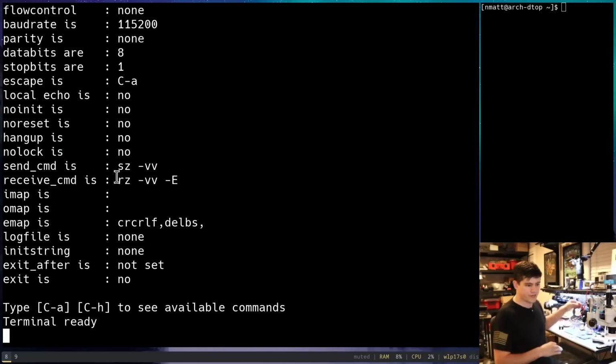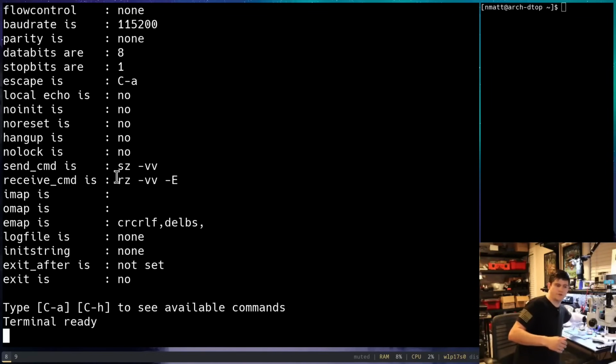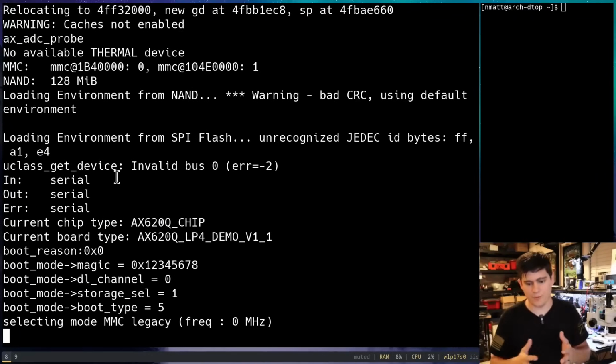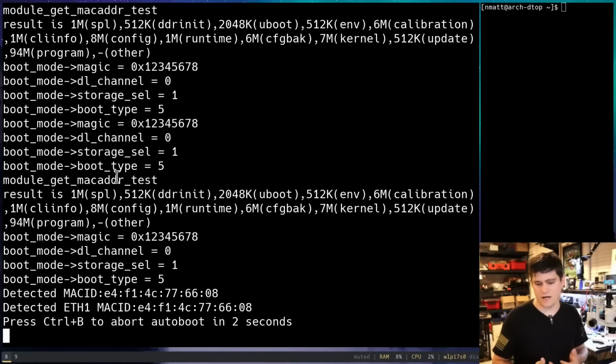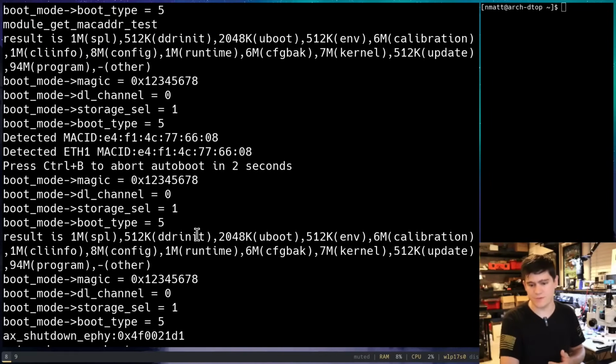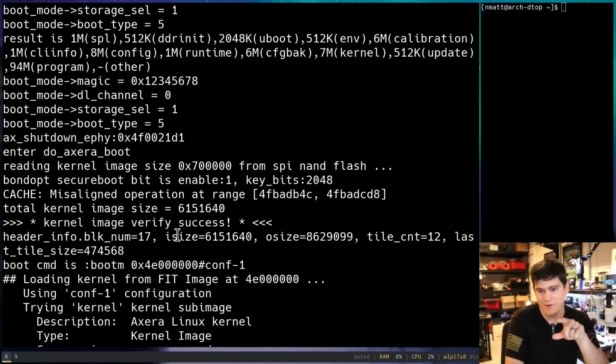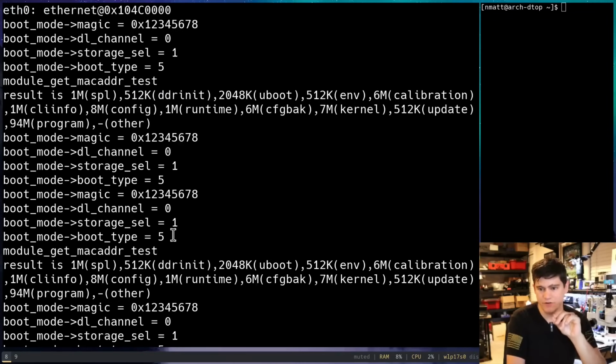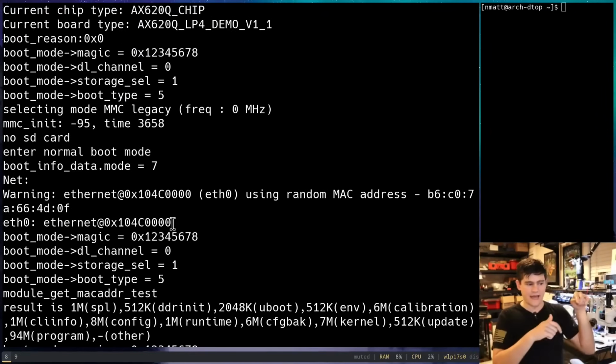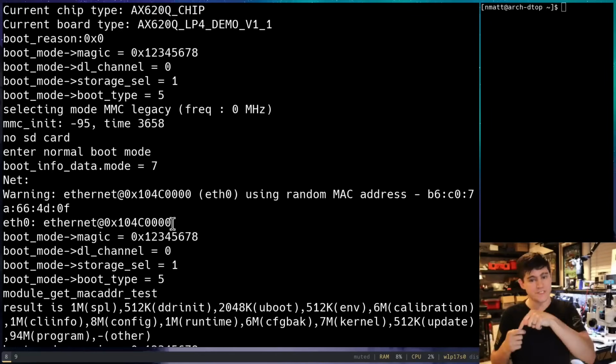Now what I'm going to do over here is power on the device. I'm going to turn on my power strip here that the PoE injector is plugged into. And if everything works correctly, we should see output. So that is awesome. We see the device booting up, and it's going to scroll, scroll, scroll, but I'm going to scroll up, and we're going to identify something that we are going to target. Right now, I don't have the other pin connected. I don't have my TiGuard board's transmit pin connected to the receive pin on the board. So we need to find which one that is.